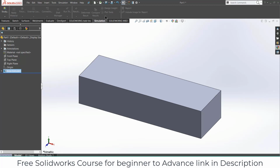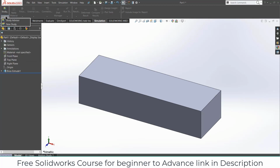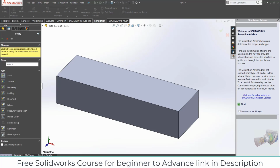So the first thing you have to do is define a study type. What kind of study are you going to do? So click here, click on new study. Just in case anybody is wondering what the study advisor is, when you click on it, it basically guides beginners on how to do SolidWorks simulation, but I don't want it, so ignore that.